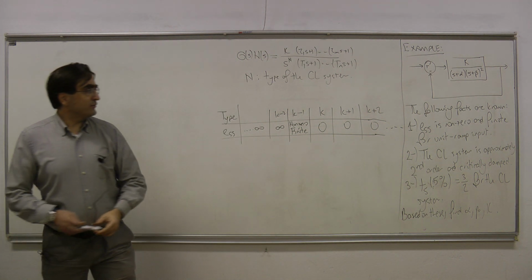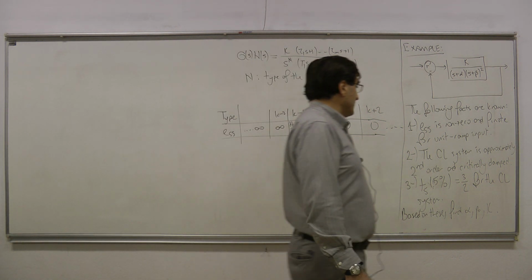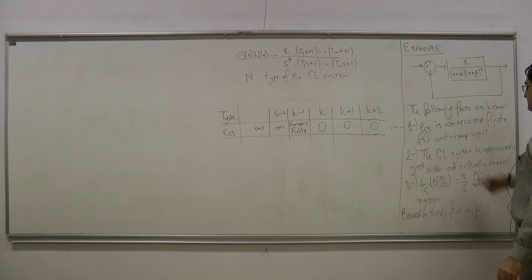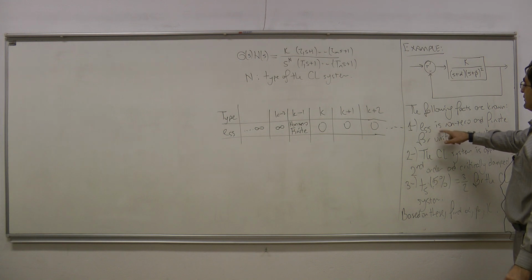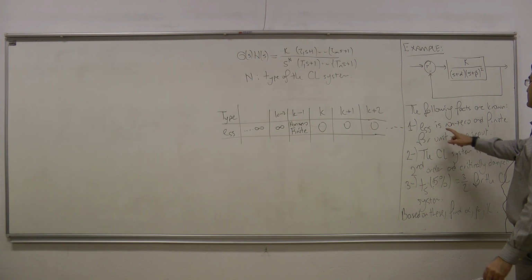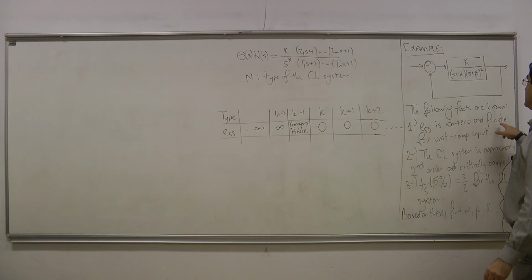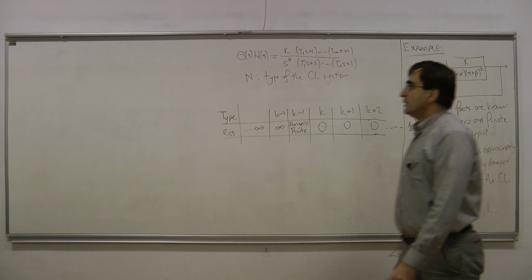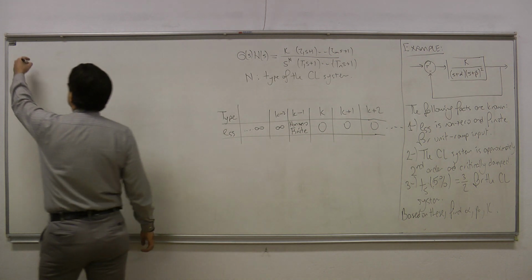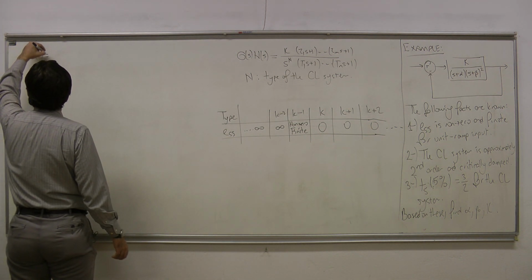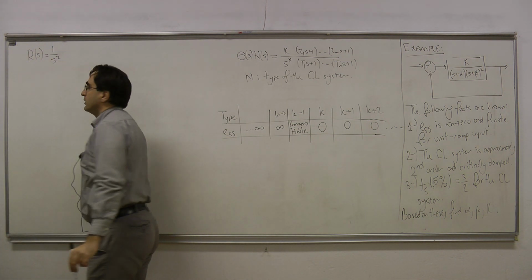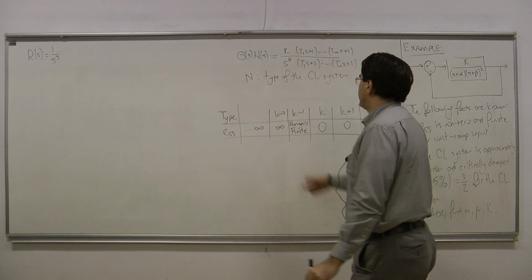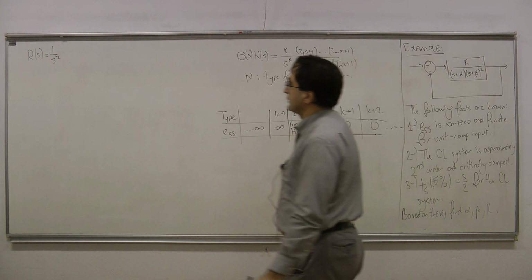So this is our question. Now let us try to examine these characteristics one by one. So the first characteristic is that the steady state error is non-zero and finite for the unit ramp input. Okay? What is unit ramp in Laplace domain? We know that R of S for the unit ramp is 1/s squared. All right? Therefore, in this table, K is equal to 2.